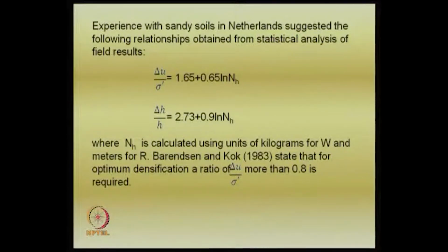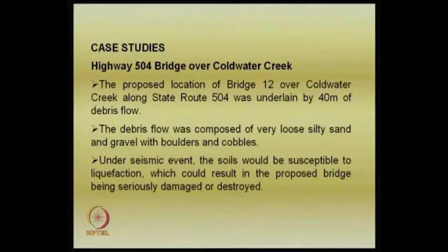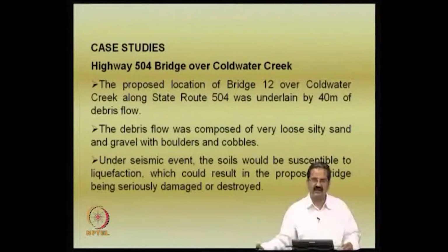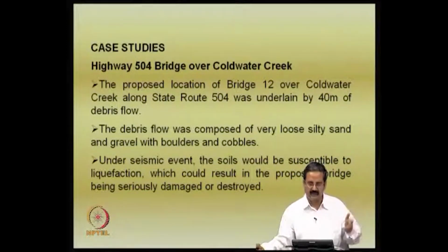guidelines. In fact, the best way would be to do a field case study, in which the first thing you should do is a trial test. Say I have done it using a charge of 1 ton or say 500 kgs. What is the distance at which the area gets liquefied? You must be able to roughly calculate depending on the soil type, and then use that as a basis for refining your designs.